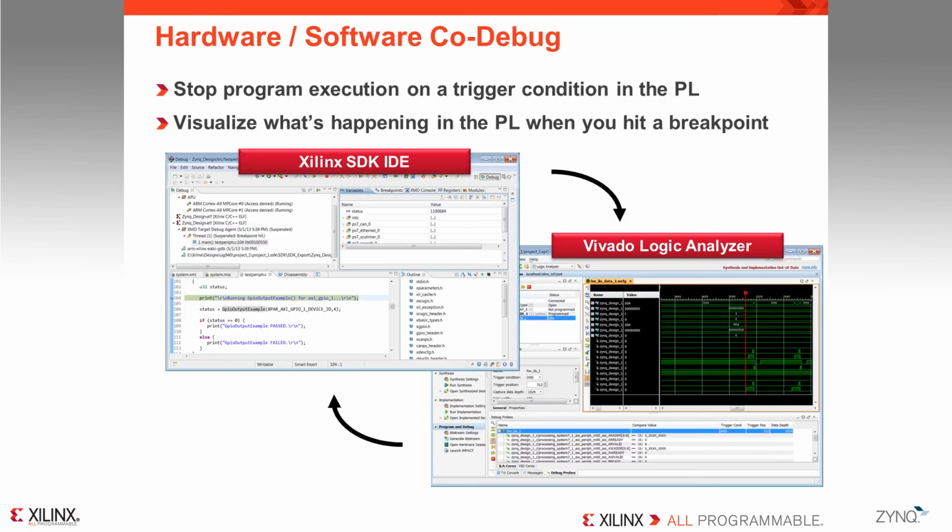Ever wonder what the hardware outside your application's processor is doing in response to your code? With the Vivado Logic Analyzer, you can stop program execution based on a hardware trigger or see what is happening in the programmable logic when you reach a breakpoint in your code.